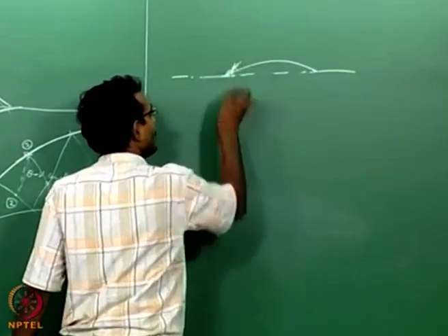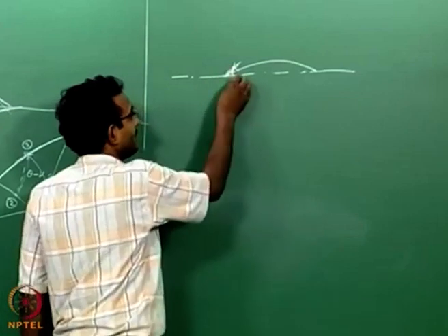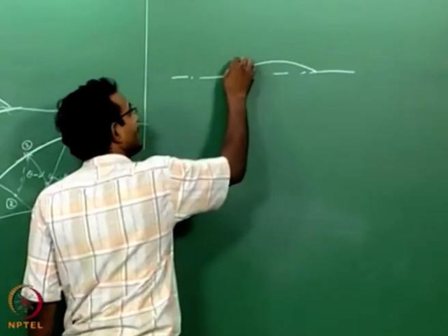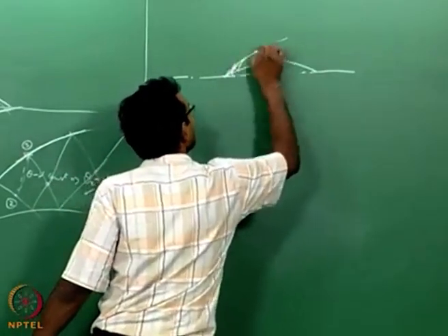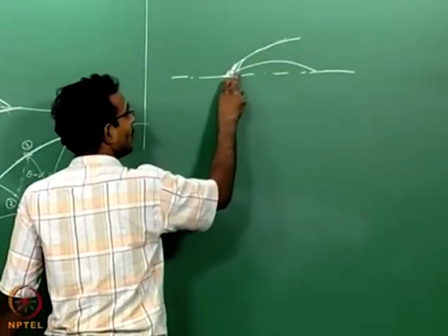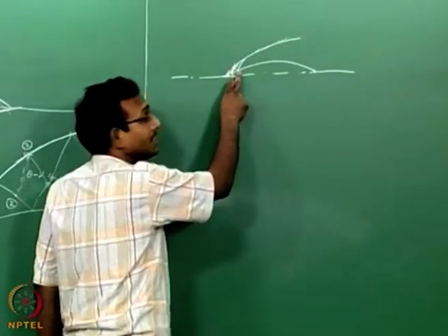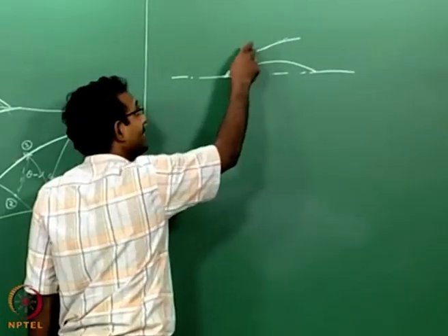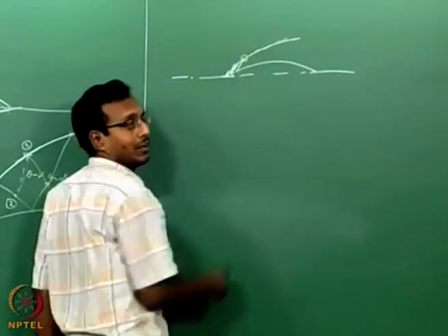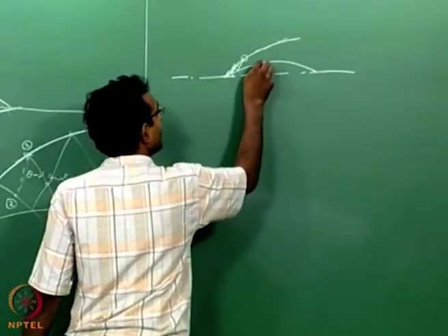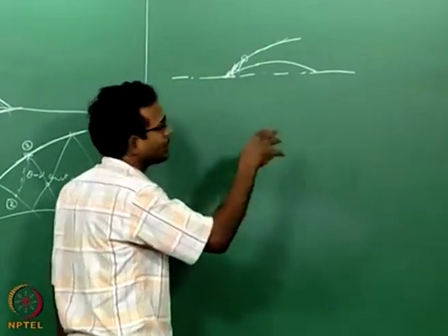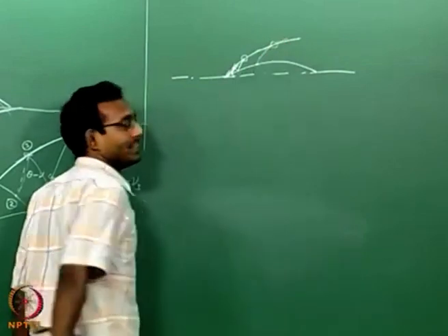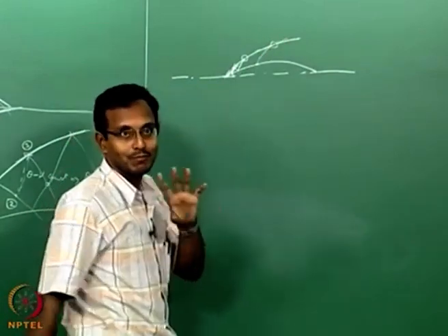Similarly, I can start now solving this characteristic this way, which will send out a characteristic, and then I will now get the next point there. Like that I can start getting, and eventually I will start having a full shock which will be curving based on the local wall angles here. This local wall angle decides my theta minus nu on this characteristic line, which will decide the theta minus nu at that local point on the shock. Similarly here, theta will be a lower value, so theta minus nu will be different from here, and so this will decide the shock point there. Which is also telling you some gas dynamics physics.